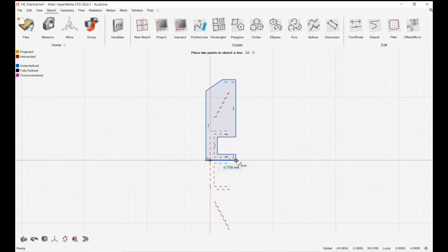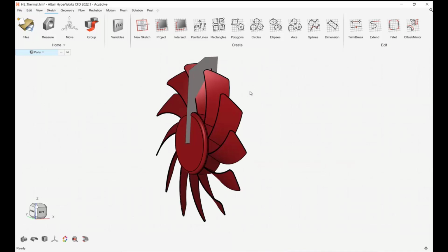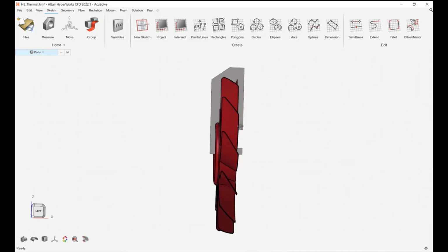As soon as the lines are closed, you will see that region as blue. That means it's a closed loop from which a surface can be created. There are legends if you want to add constraints, based on the definition. Right now all the lines are unconstrained, or the dimensions are not defined, but you can define the dimensions and some constraints for each of the lines within the sketch ribbon. So it's pretty extensive capabilities. It's a fully featured sketching ribbon. Once you are done, you can just press escape or exit out of the tool, and you can see that the ribbon surface will be created.